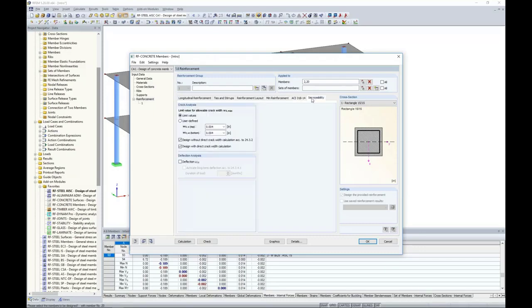And finally, we have our serviceability tab. So we can design according to crack width. We'll let you know if you are exceeding the crack width based on the value set here within this drop-down box, which is set by the ACI committee. Maybe we want the limiting crack width to be 0.12 inches. We also can take into consideration spacing considerations of the ACI reference in order to limit crack width based on our shear spacing. So the program can also account for that.